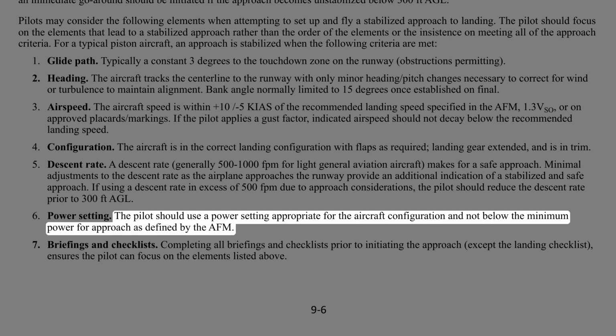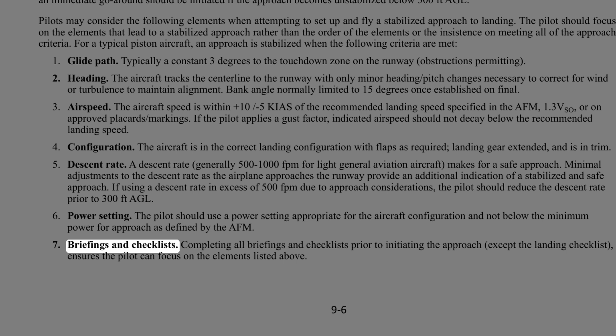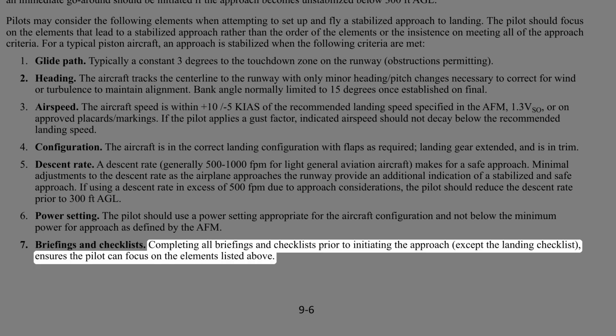Power setting, the pilot should use a power setting appropriate for the aircraft configuration and not below the minimum power for approach as defined by the AFM. Briefings and checklists, completing all briefings and checklists prior to initiating the approach, except the landing checklist, ensures the pilot can focus on the elements listed above.